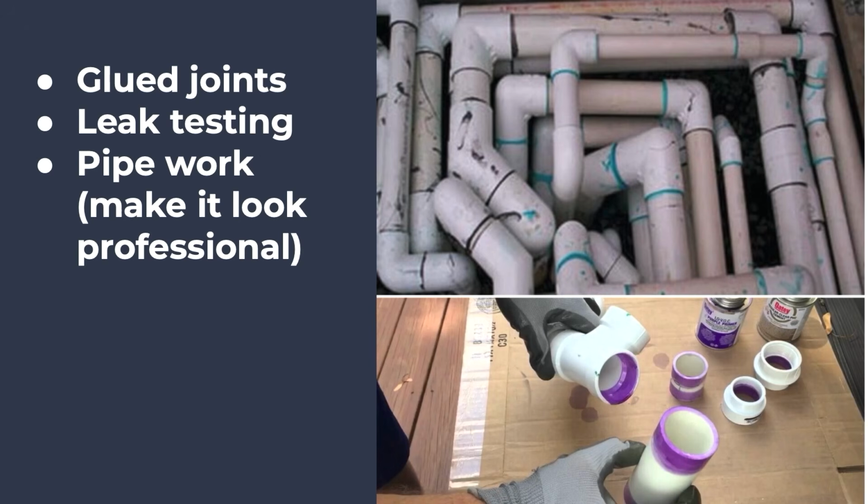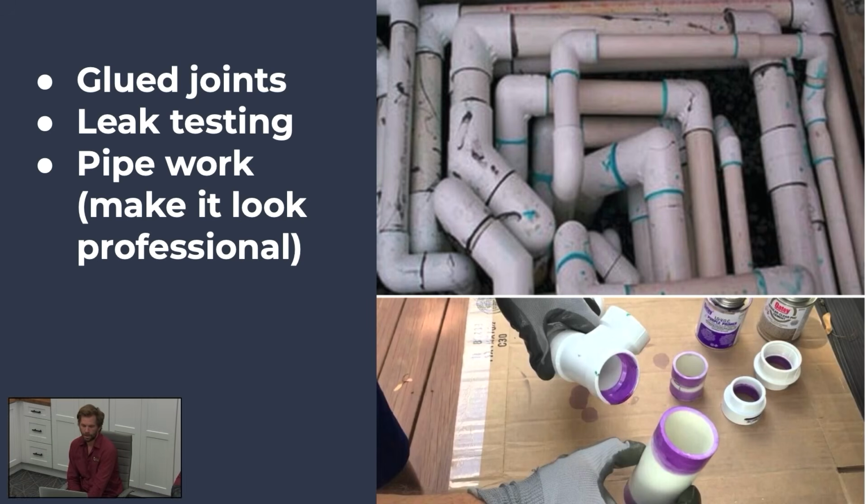I left this one here just because it's a common issue and you guys will do some repairs. When you do a pool heater high pressure joint, prime it first, and then when you use your glue, hold the connection in place for at least 30 seconds.